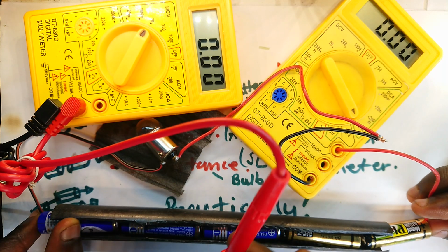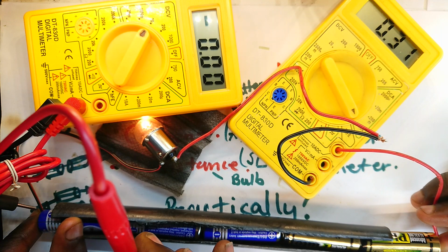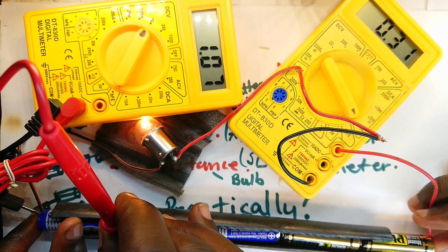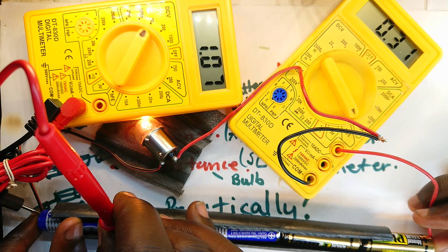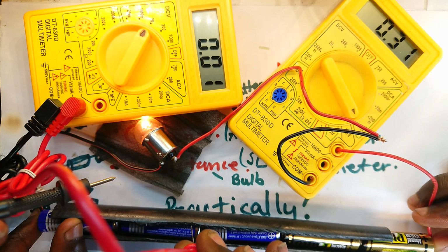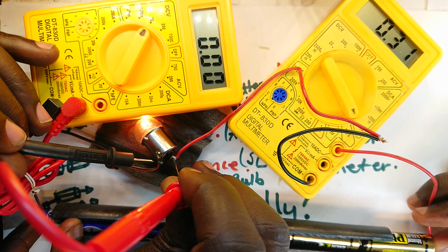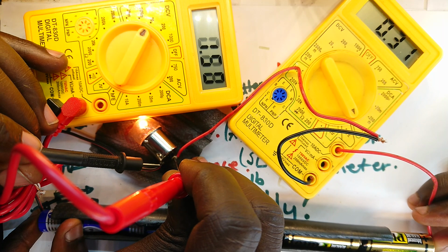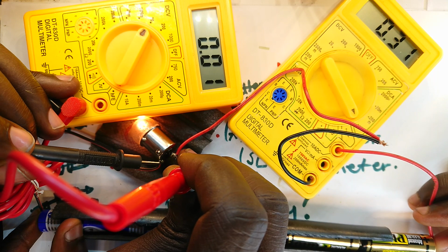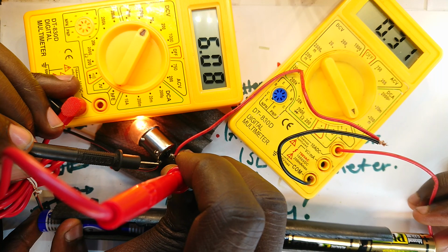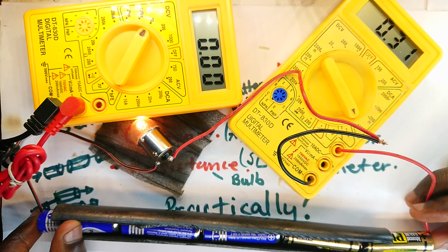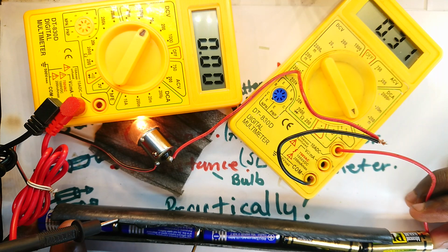So your circuit is not complete, like that. Now measure the voltage across this. When power is flowing, you see it's dropped to 1.07. So when current is flowing, the voltage drops. But let me also measure the voltage at the bulb, and see it is dropped to, because remember we are supplying it from a 7.5, it is dropped to 6.5. That's because current is being drawn. And so I've just demonstrated that when you're measuring voltage, the voltmeter has to be in parallel.